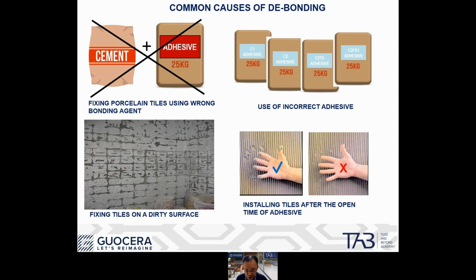Now, we come to the reason why cement doesn't work well to bond porcelain tile. To explain this, remember my table of the 5 different categories or types of tiles. I did mention porcelain tile has a water absorption very close to 0, less than 0.5%, which means a piece of porcelain tile is just like a piece of glass. Now, if you talk to contractors, they will know.